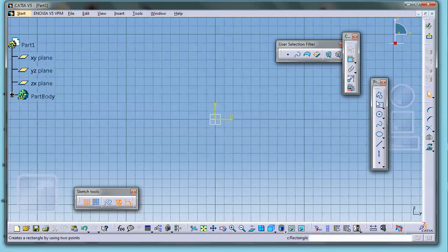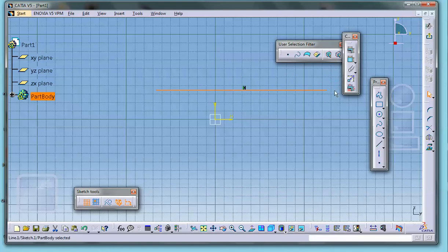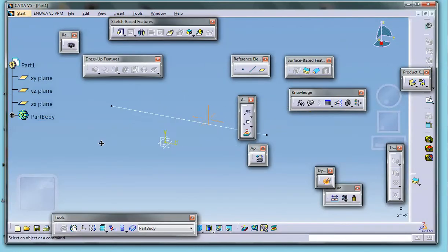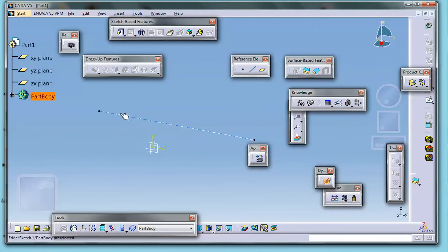There is one other step that you have to go through here. When you create your geometry, which is later to be modeled with beam elements, you've got to join this geometry. Joining is done in wireframe and surface design.